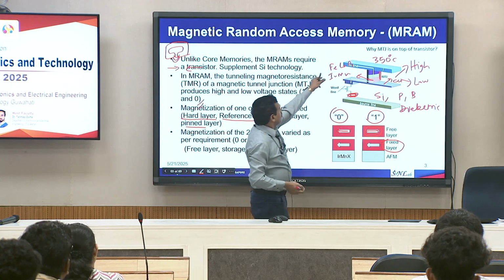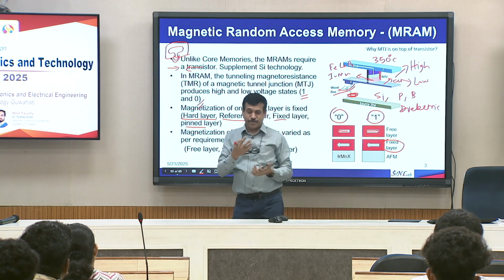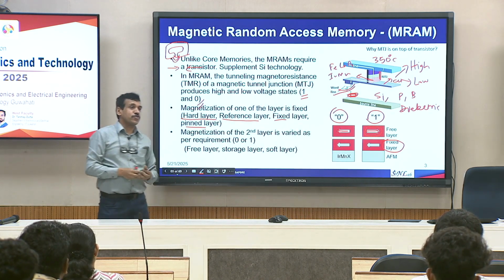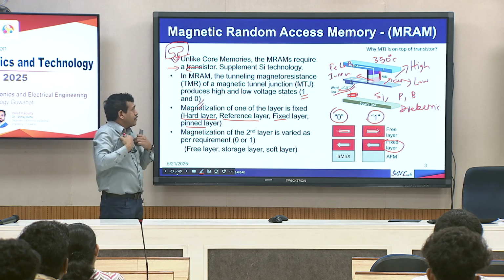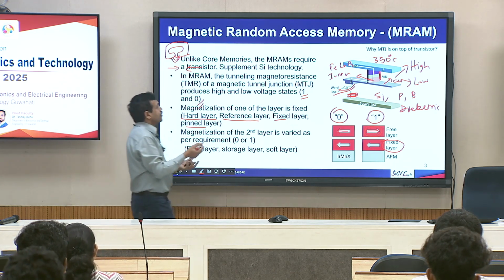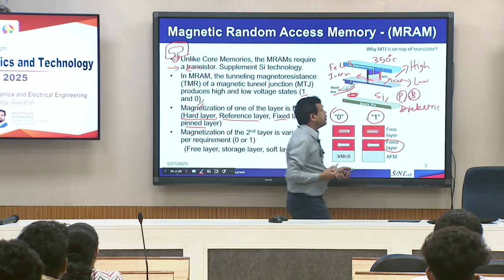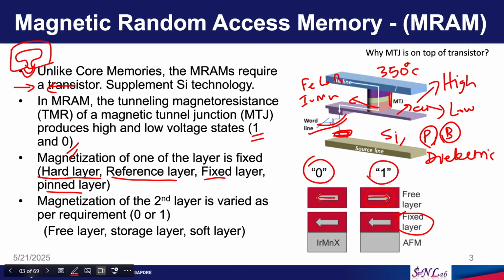All these cobalt, manganese, they will go into the transistor element. You know the semiconductor chip is supposed to be very clean, it is a semiconductor material, right. You are controlling the doping very precisely. So, if you have all these elements and do annealing at 350 degrees Celsius, all these materials will go inside your semiconductor chip and your transistor won't function.